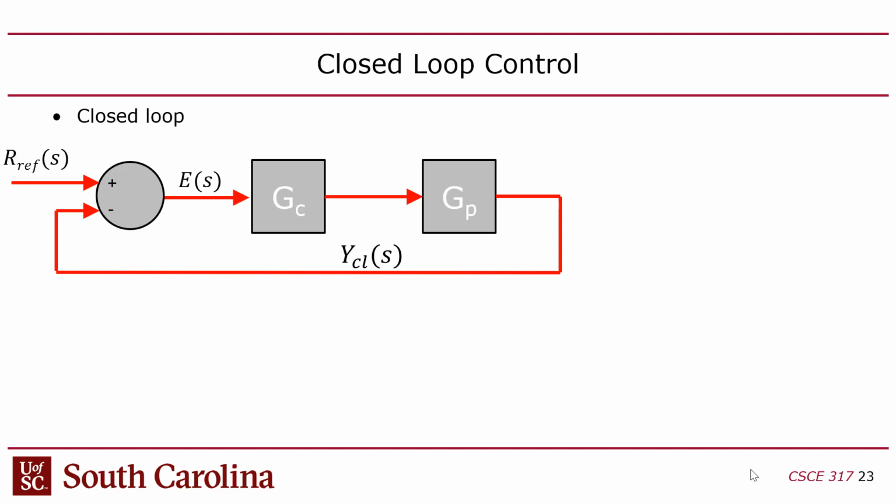And then once I have that transfer function, I can check to see if it's stable. And if it's stable, then I can also check other things like how long it takes to reach the set point, and how far I overshoot. There are other performance factors you're interested in with control design, like how good the controller is. Well, it's stable, but it takes a while to get to the set point. Those are the things we want to know. So first we have to build the transfer function. This is a little strange, so try to follow me here.